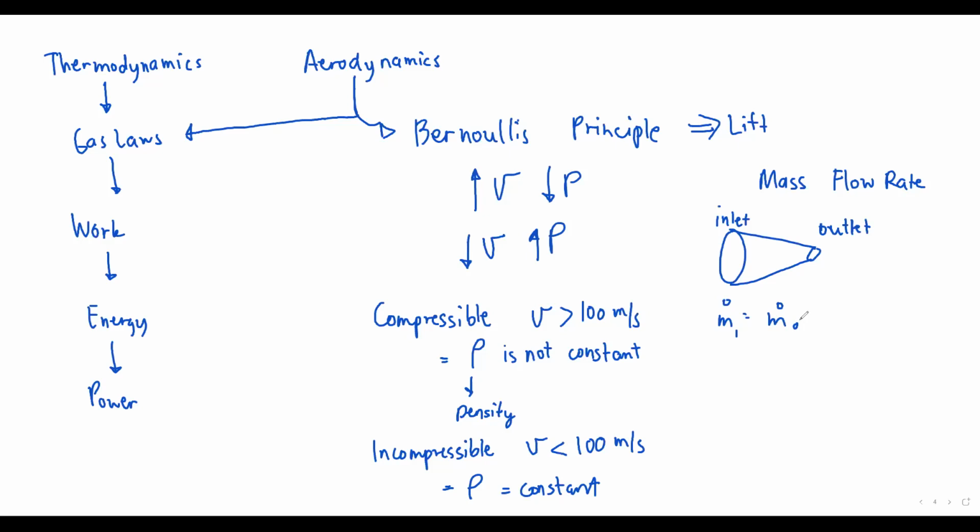So if the flow rate at inlet and outlet are equal, of course ang formula natin guys is rho multiplied by area times velocity. Constant daw yan. Yung flow rate natin is constant at every part, so equal dito at equal sa outlet. From this idea, rho1 A1 V1 is equal to rho2 A2 V2. And then, let's say that the fluid is incompressible.